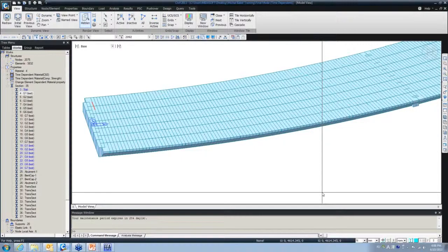So you can use any section, but normally we use the same thickness as the top slab. So for this model, we can use the top flange elements. The transfer elements technically ensure that the girders are working together, and also ensure that there is torsional stiffness or lateral stiffness in that direction.